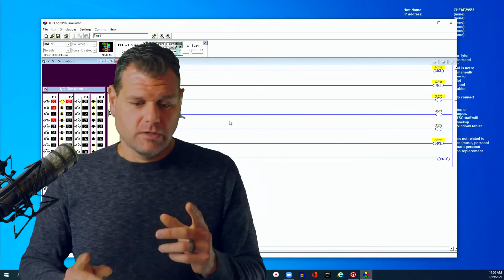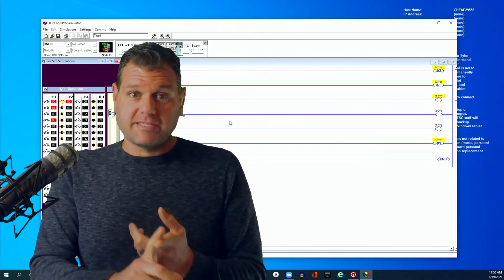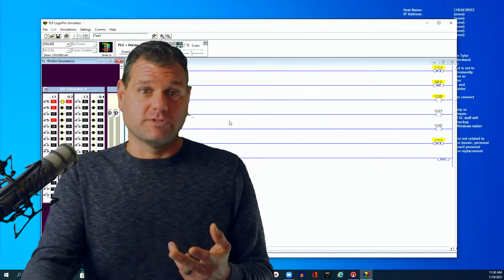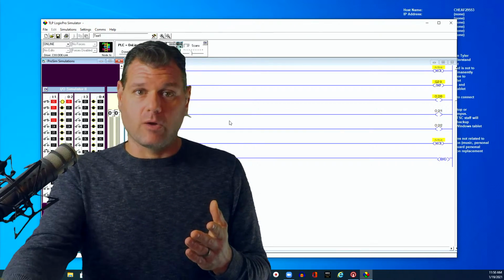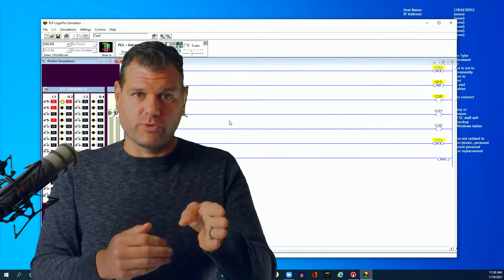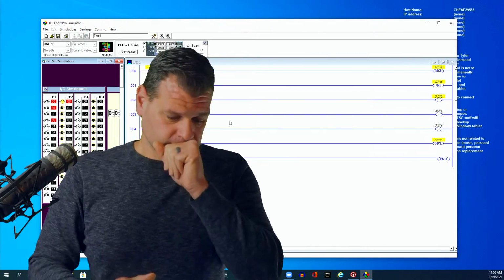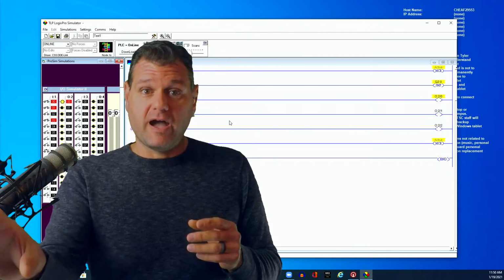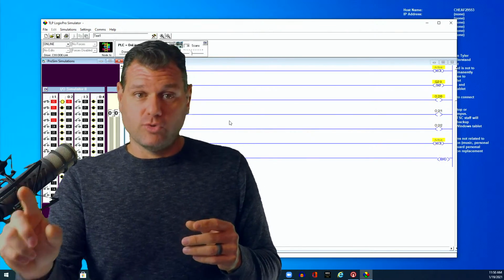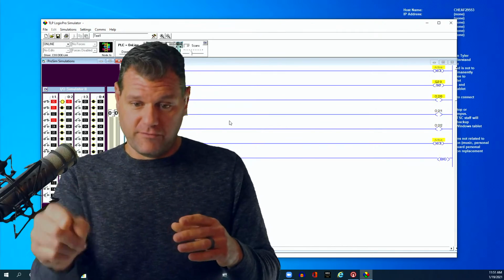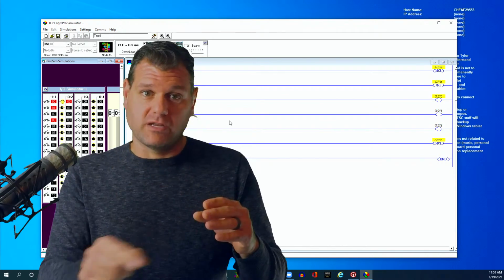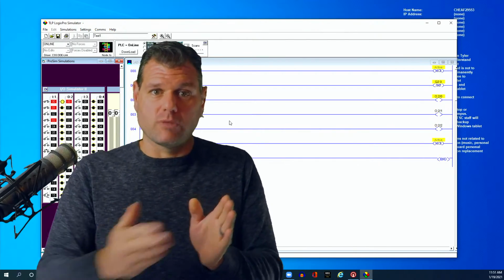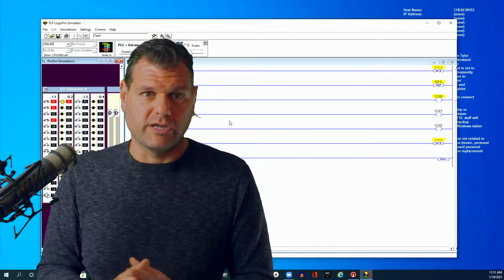Also, a couple things. You can nest, which means you can jump to a subroutine from a subroutine. Just be careful. You can jump so far out that you can leave 3 and go to 4, and 4 to go to 5, and so on. But by nature, when you finish scanning 5, you have to finish 4 where you left off, and then go back to 3 and finish scanning 3, and so on, right? So it might take too long to go out and all the way back if you keep nesting. You can nest 2 or 3 times, that's fine.